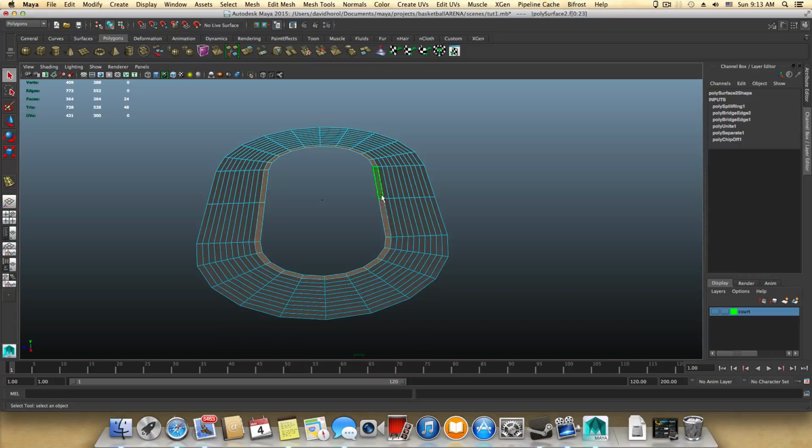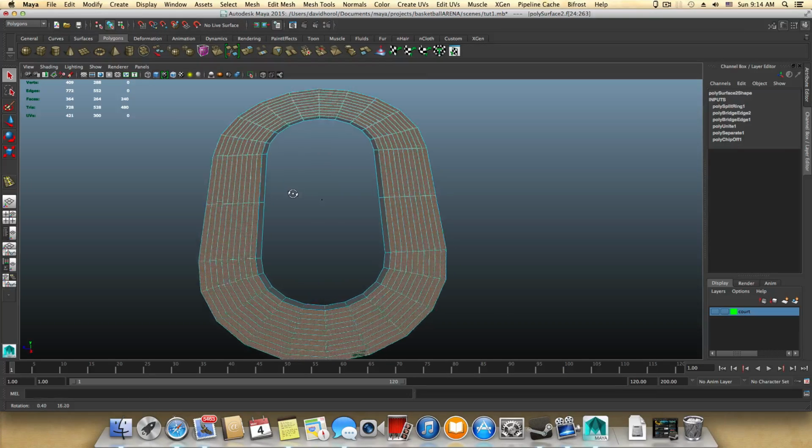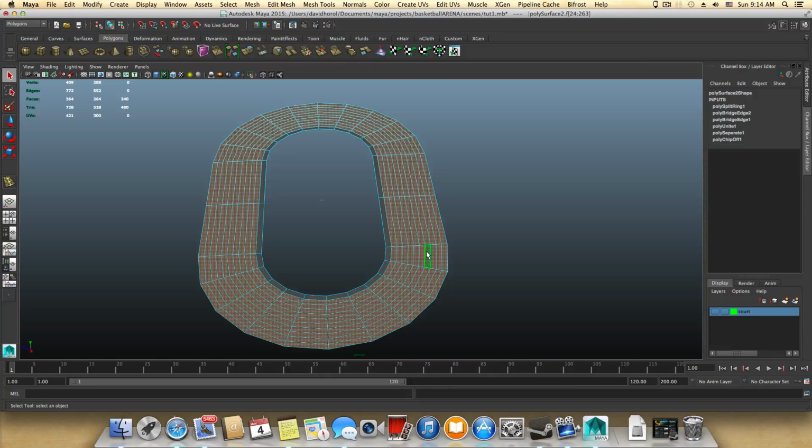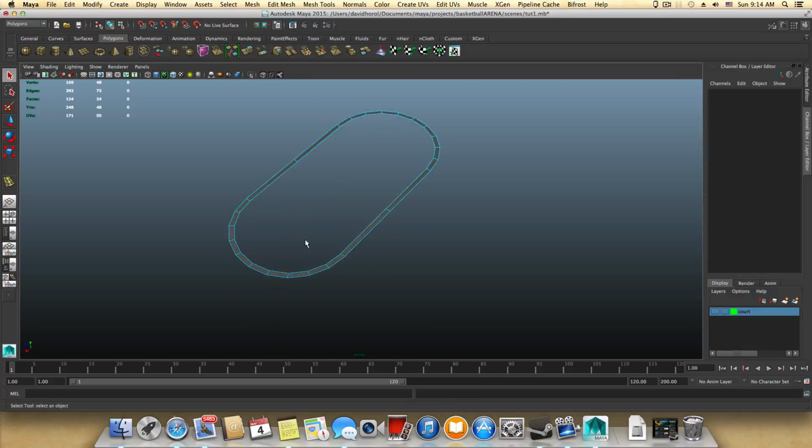Now, we only need this thing here, the rest we need to delete. So what you want to do is hold shift and mark-select everything here. Because we already selected the inner circle, and now we are using the marking selection tool, this will invert the selection, okay, while you release this. So everything here that we don't need has been selected, and what we still need is unselected. So you can simply press the delete key on your keyboard, and it will delete the rest of it.